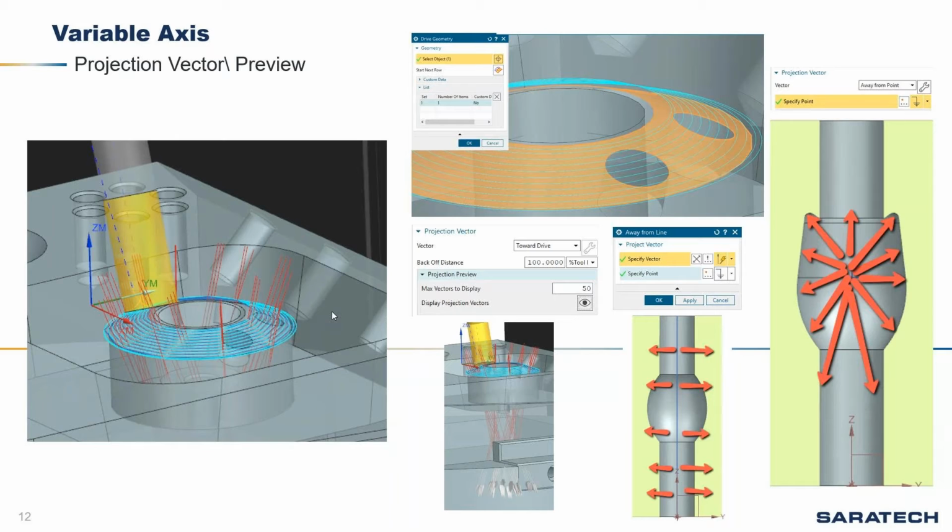So if I was trying to do an internal surface like that with a spherical cutter, that would be sufficient to cut that because none of the two corners have any type of undercutting to it. So imagine yourself standing on that line, walking around the cylinder in a circle. Whatever you're capable of seeing is what's capable of being cut.